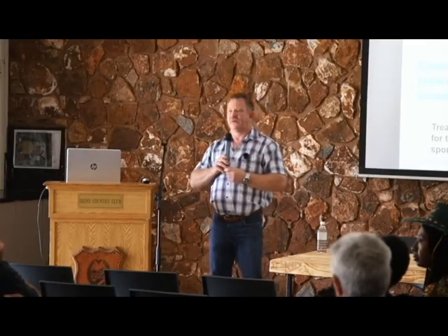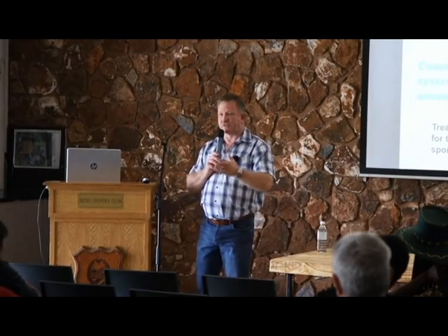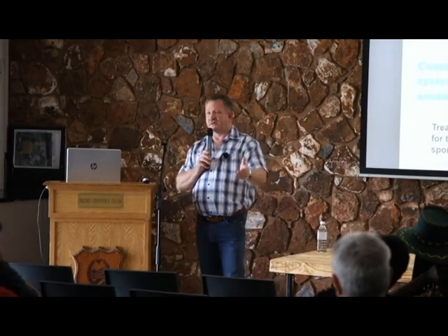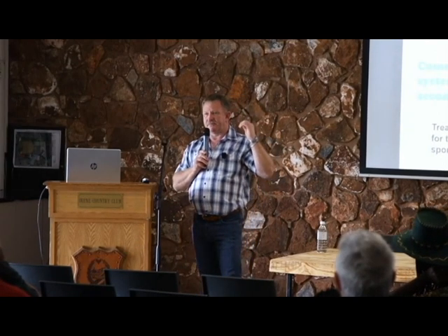Yes, sir. Maintenance on the greywater systems at that first chamber, is it a regular thing? Obviously, it depends on the density and the chemical use, but what's the maintenance on the first chamber of that greywater system? It very much depends on abuse. If you have, for instance, a few people living there with long hair, then you'll maintain it more often than short hair. It depends on what you put down the drain at the end of the day. That specific one that you saw there was the first prototype I installed in my house in Cape Town.